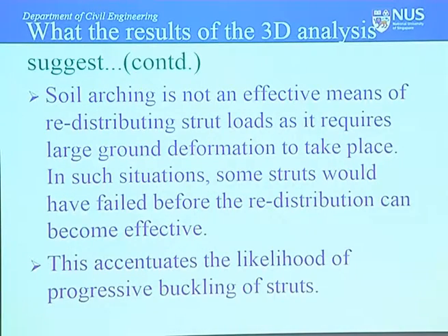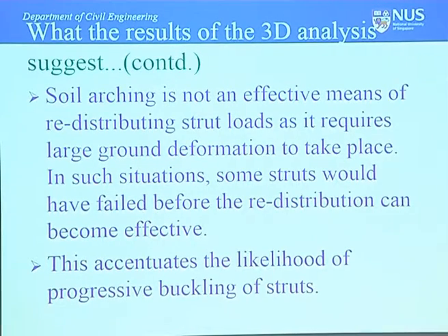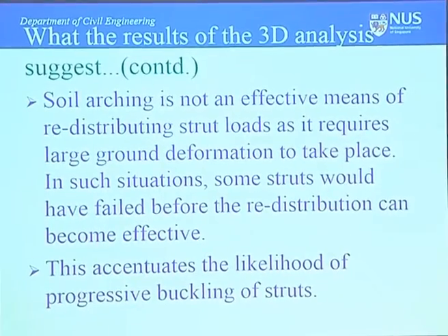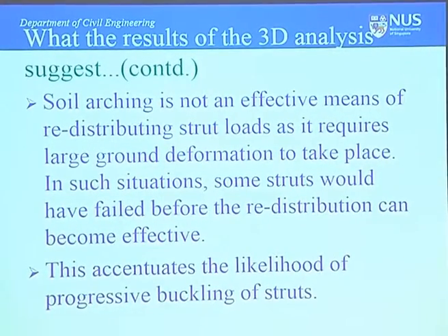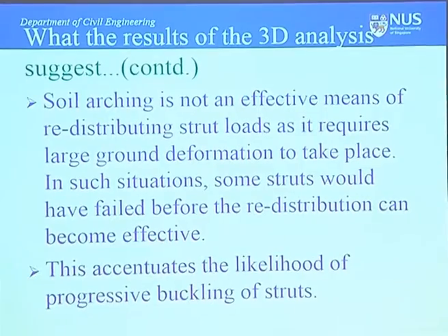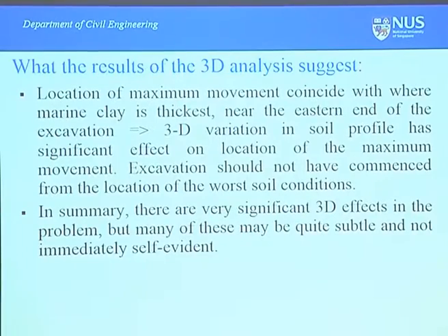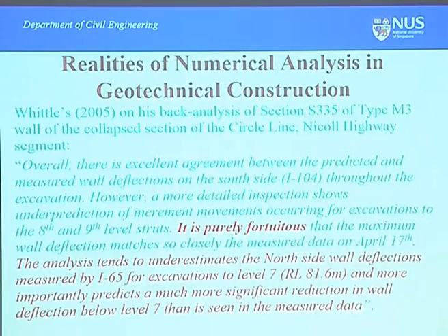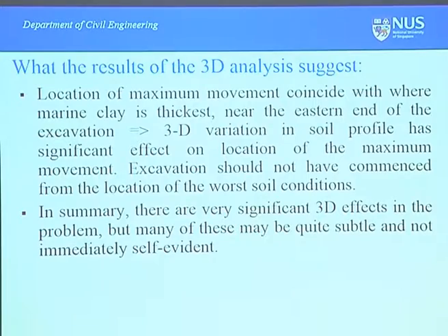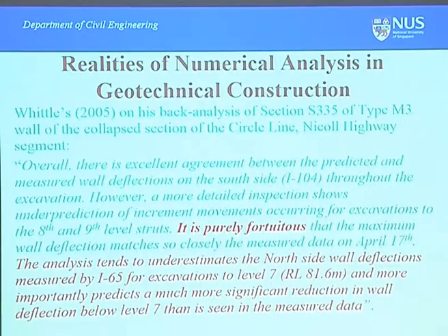So this is it. Okay? Now, the question is whether soil arching is an effective means of redistributing strut load. My personal sense is that we shouldn't rely too much on soil arching between panels of the diaphragm wall, because you really need a lot of differential movement, especially for soft soil. So this is not a good way of utilizing soil strength. I think it's a very risky way of doing it. So basically, what I hope to use this to show you without going through any more of the thing, essentially, is that let's see here.